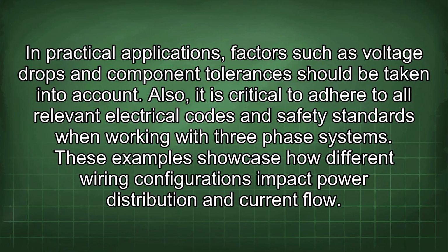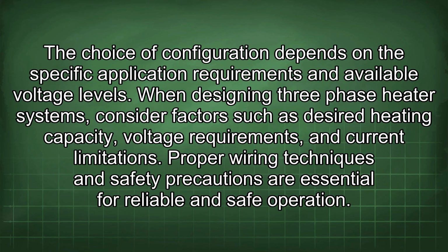These examples showcase how different wiring configurations impact power distribution and current flow. The choice of configuration depends on the specific application requirements and available voltage levels. When designing three-phase heater systems, consider factors such as desired heating capacity, voltage requirements, and current limitations.